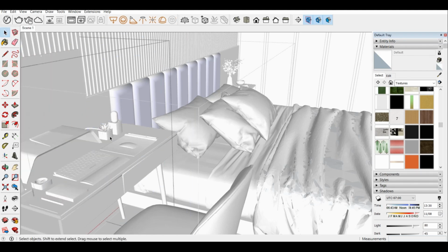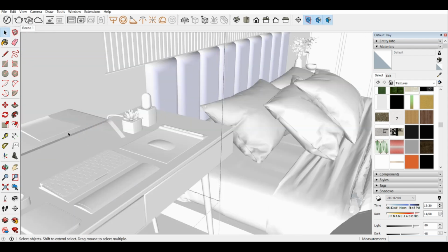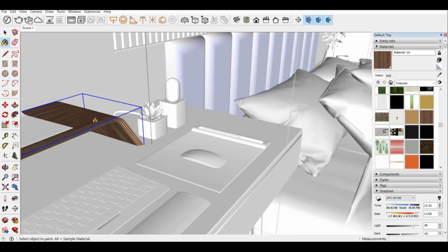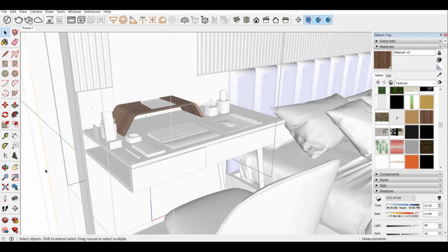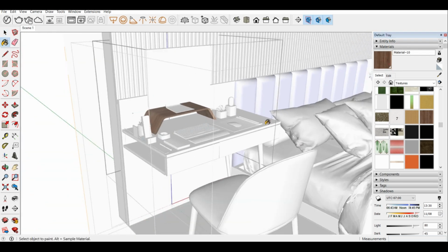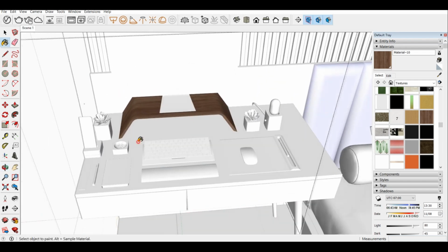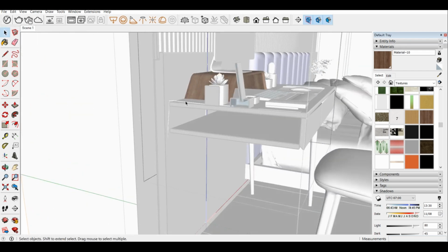Now we will be getting into this group. If it's not coming in, then you have to zoom out for a bit. Now it's able to get the texture. You can see we have nicely placed the texture there. Now we will be selecting the tabletop. One second, you have to scroll back and zoom out for a bit, because a few times the texture doesn't get imported due to the geometry selection. You can even use the Escape key.